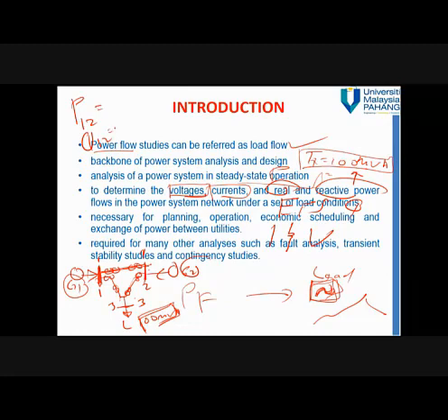So we have to calculate all these values. And then so on for bus bar 2 to 3 and 1 to 3. We have to calculate the power flows. Okay, then we can see whether the current is within the limits of this equipment capacity. That is power flow.